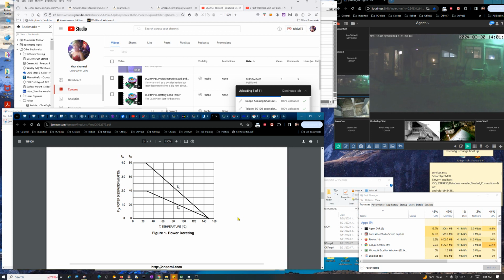So it's good just to be around there somewhere. But even in the case of forced air cooling, you might be better off measuring the temperature slightly below the component on a vertically mounted circuit board. That's my opinion, and it's just a matter of thinking through it logically.